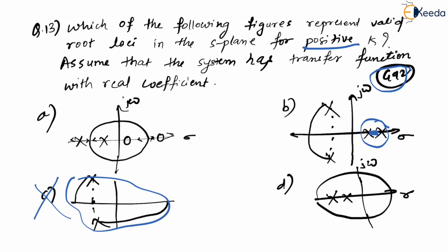One pole means an odd number of poles and zeros, which means this is definitely a root locus area. Which means breakaway must have happened here, but breakaway has not happened. Similarly, the root locus starts at a pole and should enter into another pole, and this also doesn't happen. So option B is also wrong.